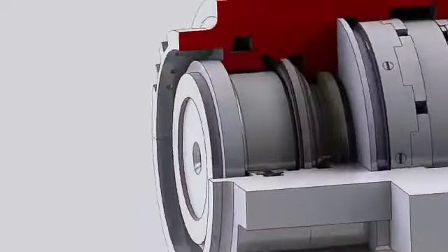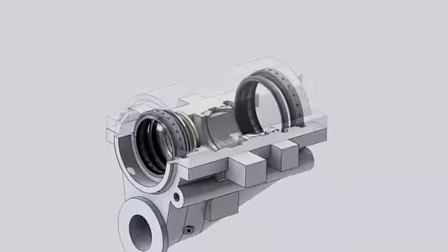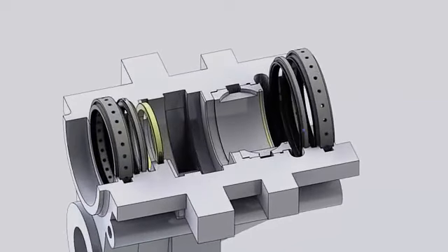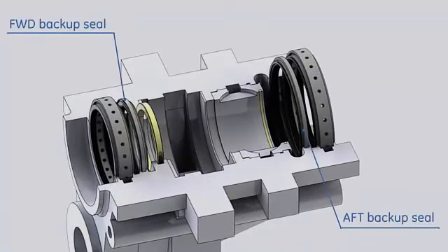Between the 2 rows of seal teeth, sealing air is admitted through multiple radial holes to stop oil from spreading along the shaft. Some of this air returns with the lube oil and is vented through the lube oil mist eliminator, and some escapes out of the housing. Inboard of the main pressurized seals, 2 backup labyrinth seals are installed for positive sealing.